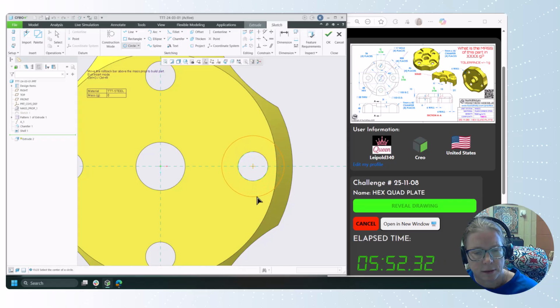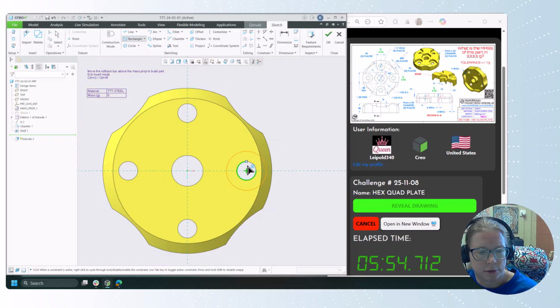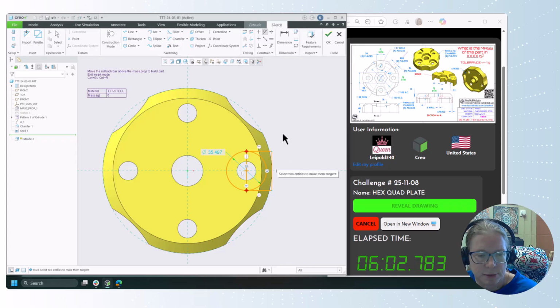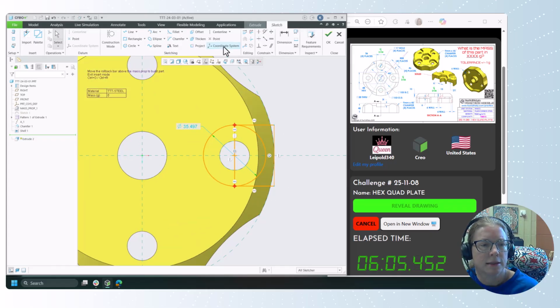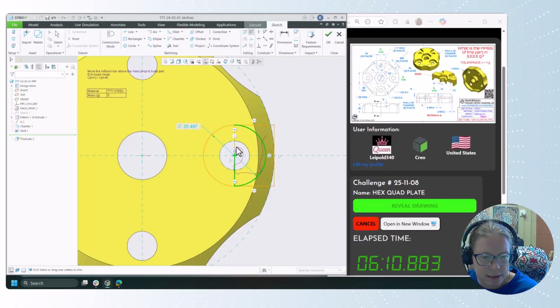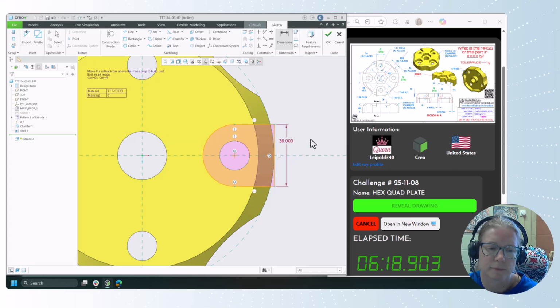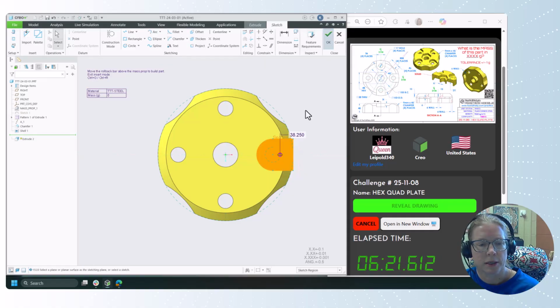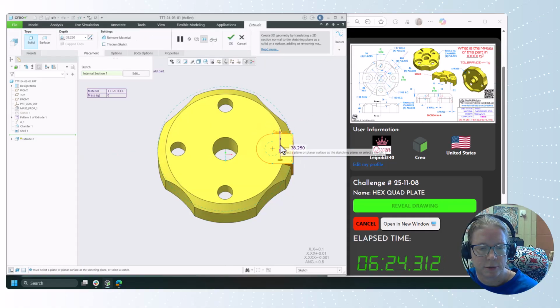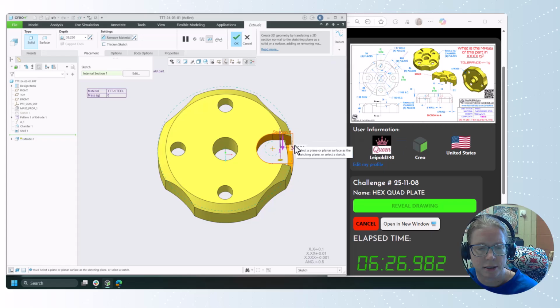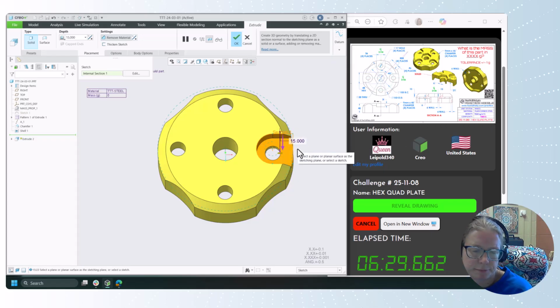Make something like this, and then we'll do a rectangle. And I like to reduce how many dimensions I'm using so I can use tangent. Let's grab the delete segment and get rid of these inner pieces. And all we need then is the dimension of the width. Okay. So we're gonna flip that the other way. We're gonna remove material. We're gonna set the depth here to 15.